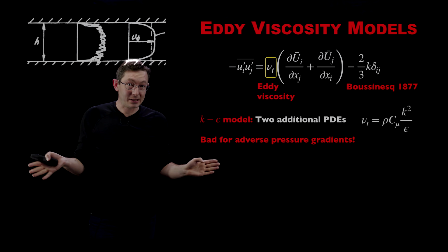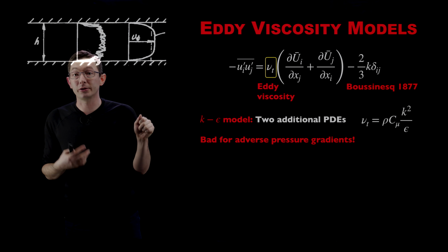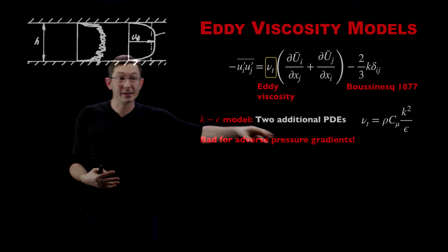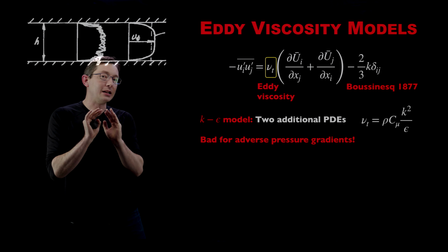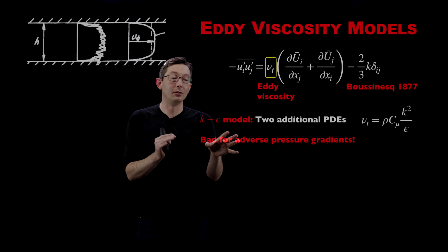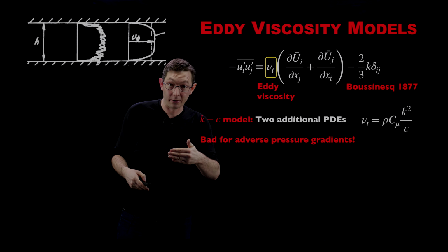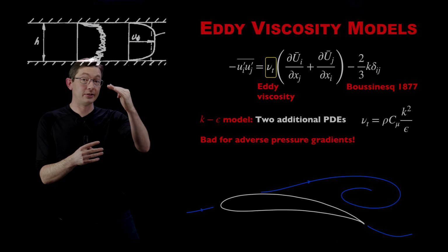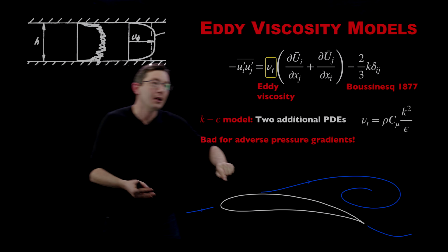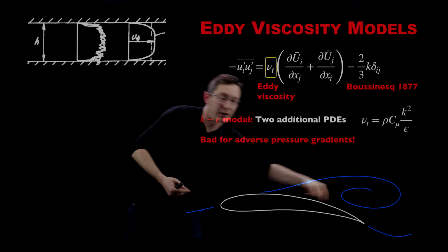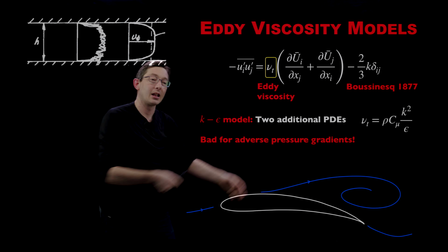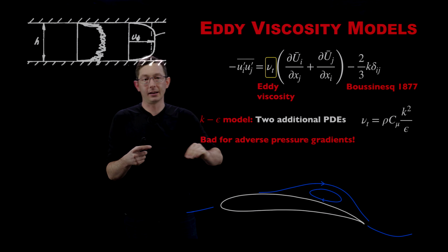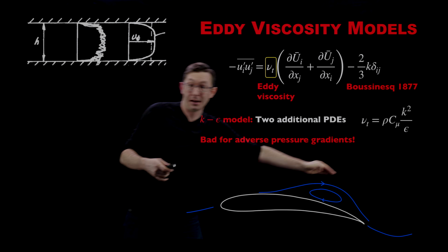Now, again, K epsilon models, if you run any commercial turbulence software, there's an option for what turbulence model you want to select or to use, and K epsilon is one of the standard models. But it's been known for a long time that this is not a good model when you have adverse pressure gradients or reverse flow. So for example, if I have flow over a wing and my wing's at a high angle of attack, or it's a droop wing, or there's a gust, I'm going to get this separated flow structure that's going to cause vortex shedding. And if I look at my average flow, my mean flow, it's going to look like a separation bubble. It's going to look like the flow separates and reattaches at some point.